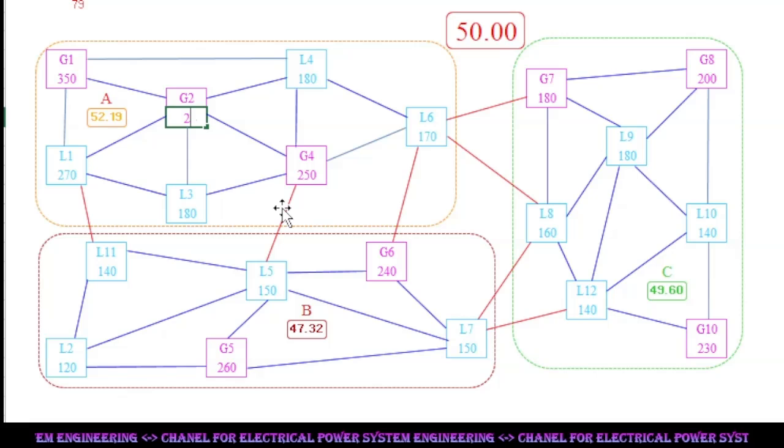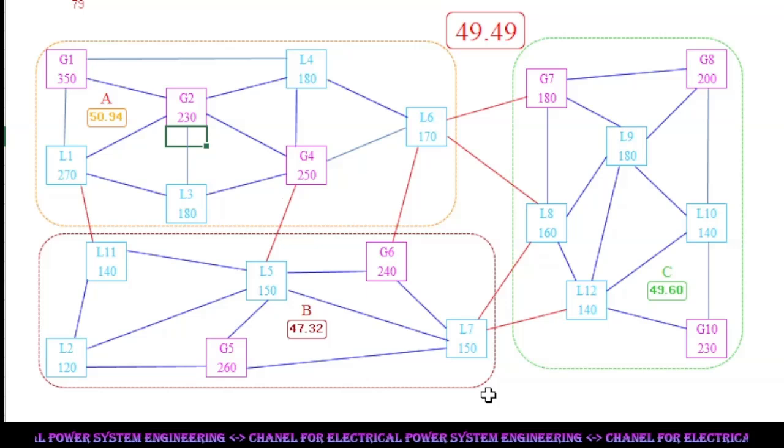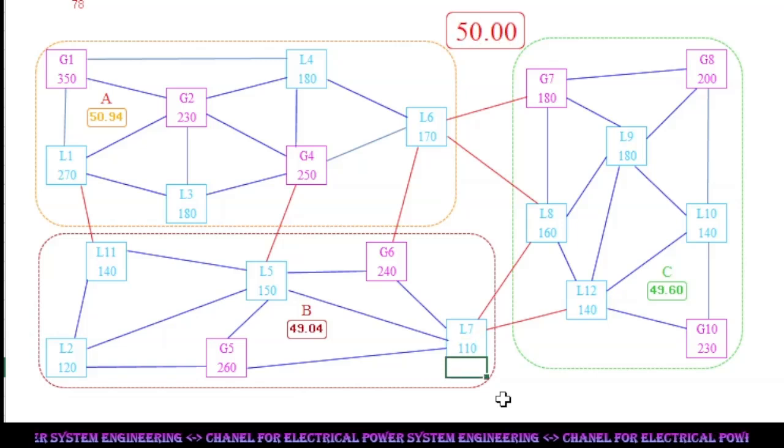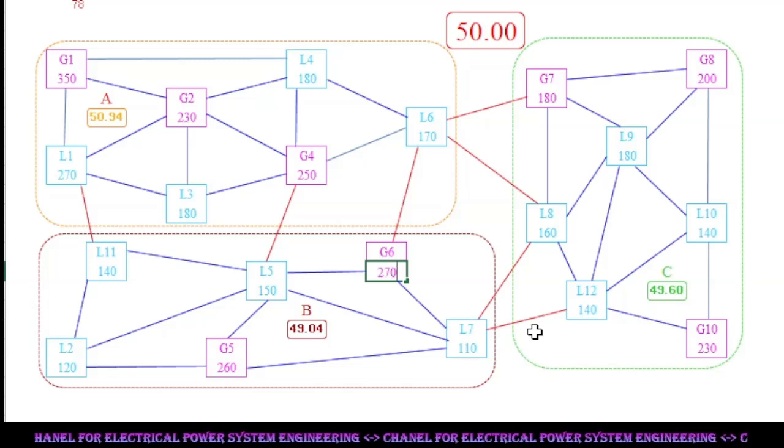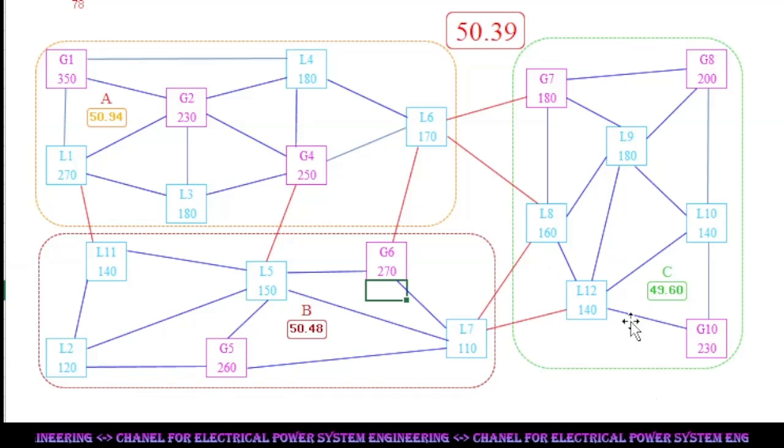Grid frequency responds to all rise and drop of load and generation at any power plant or load center in any system, whereas isolated system frequency is confined to changes within the system. So there may be a condition that individual system frequency is abnormally high or low but grid frequency is well within operating range and operates smoothly. Individual system abnormal frequency is ineffective and has no adverse impact.